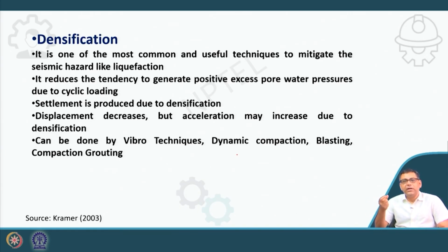So, when there is seismic loading, dilatancy may occur, which reduces the generation of positive water pressure, because we know that because of dilatancy the water pressure is negative. So, if the tendency of generation of positive water pressure is reduced, strain will also be reduced. Okay, so that is the idea.